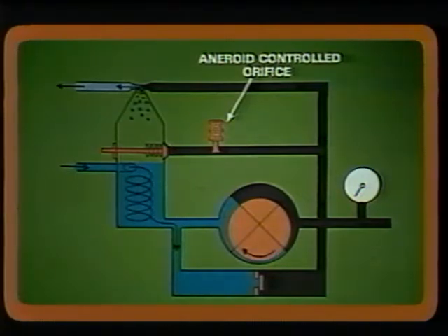But the greatest difference between a fuel injection system for a turbocharged engine and one for a normally aspirated engine lies in the injector pump itself. The orifice in the pump for a turbocharged engine is variable and is controlled with an aneroid, or an evacuated bellows system that senses upper deck pressure.